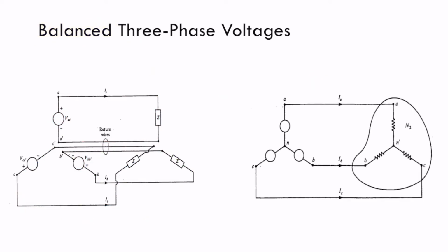What we are going to do is transform the circuit that we have here on the left to this circuit that we have here on the right. Again, this is basically the same impedance. I'm telling you that this is equivalent, and I will prove it to you in a while. So we are connecting that, and we can remove the 3 wires. At the end we will need only three wires instead of the 6 wires that we have on the left. So when we have 3 phases, and I call phase each of these circuits, we can reduce the amount of cables.